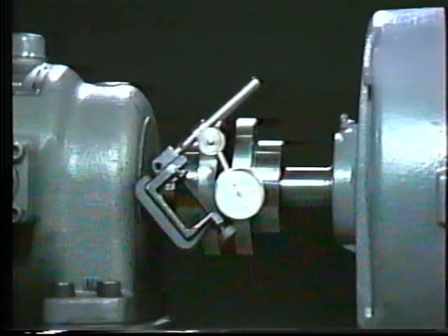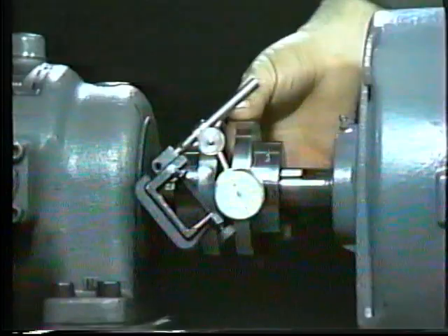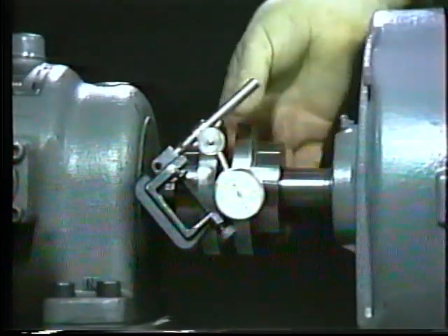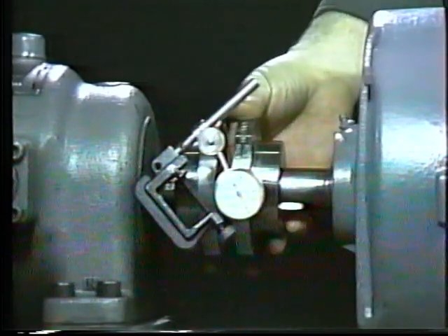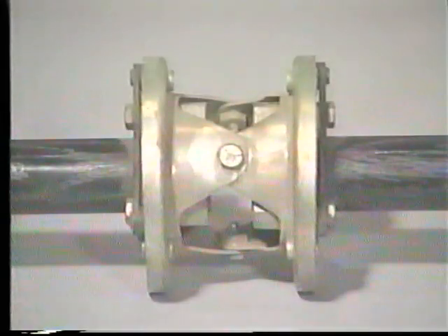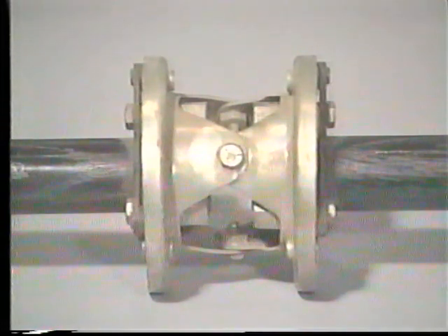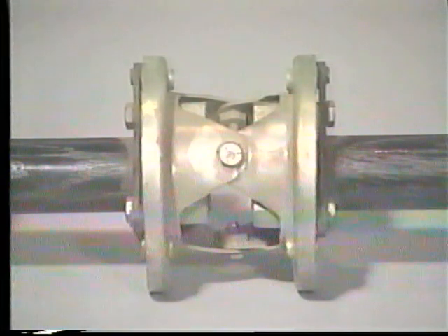There are 2 ways to overcome misalignment problems. The first is to use the greatest care when aligning 2 shafts. This is usually done when a motor or other driving unit is being installed, but alignment may have to be rechecked and adjusted periodically. The second way is to use a coupling that will compensate for any slight misalignment, which even careful alignment procedures may not be able to eliminate.